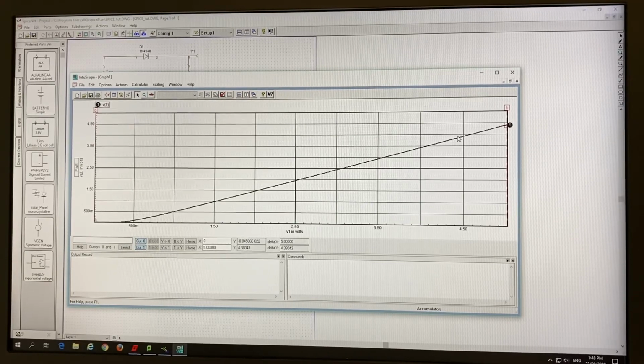But what we're interested in seeing is whether this was true. We saw that, okay, this is true. The diode won't operate before its forward bias. It will only switch on at around, in this case, this particular diode switched on at around 380 millivolts. So that was a DC sweep, just a simple DC sweep that we did.